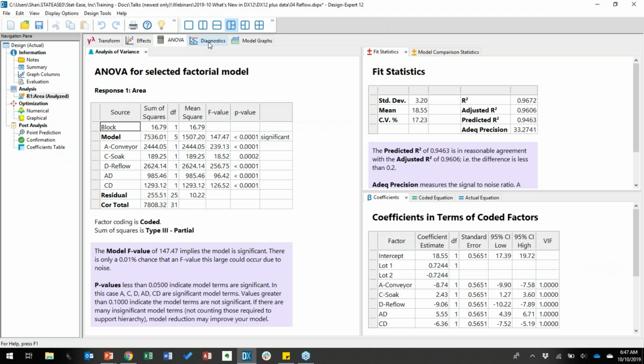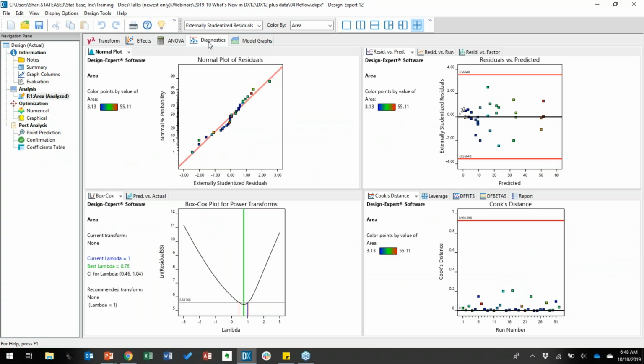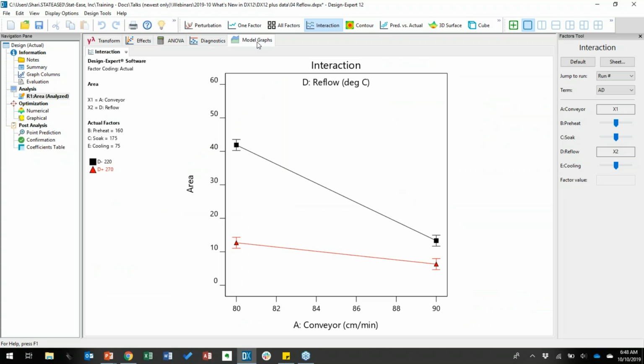All right. If you've been using Design Expert 11, then you are familiar with the diagnostics, the 4-pane view of diagnostics, which I find to be really convenient to give me a very quick view of the diagnostics, reducing the amount of time that I spend on them, but always checking your diagnostics, especially looking for outliers, using the Box-Cox plot for transformation detection. Okay, so this continues to be the same.